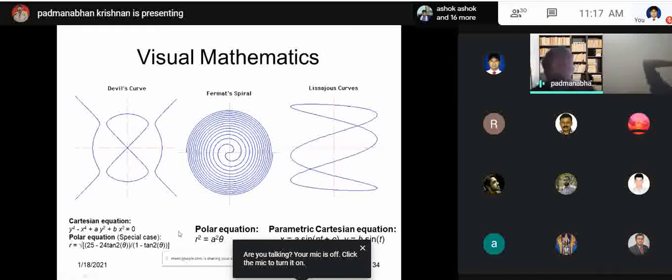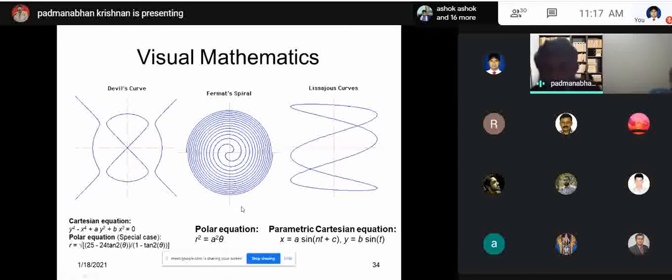You can also draw a Fermat spiral. So let's say you're modeling some kind of a spiral or rotary mechanism. A simple polar equation r squared is equal to a squared theta, plus some line thickness definitions and the interspacing definitions, would do for a Fermat spiral. Formulation is easy. If you're not using ANSYS, let's say you're using MATLAB, this becomes very important. Now Lissajous curves, I'm sure that you have heard of Lissajous curves in sound.